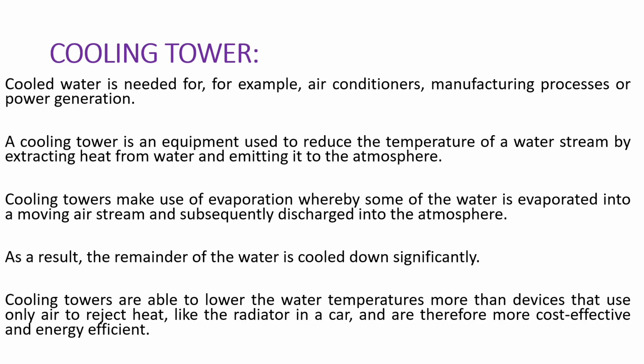So this slide introduces the main parts: frame and casing, fill, basin, fans, nozzles, drift eliminators, and air inlet. Cooling towers remove heat from hot water, and they are widely used in power plants, industries, and air conditioning systems. The cooling tower principle is that some water evaporates into moving air, and this evaporation removes heat, causing the remaining water to cool down. That's the main principle of a cooling tower.